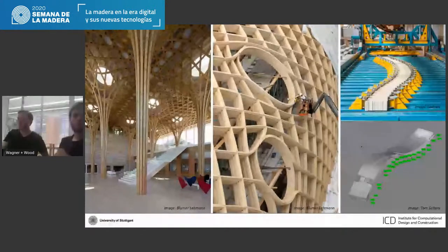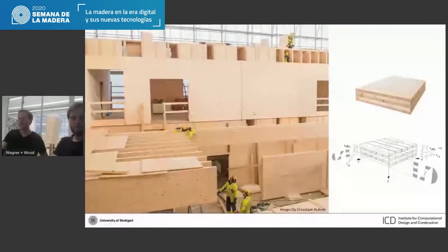But production still remains a bottleneck. To produce curved elements is complicated, and it also requires a lot more material and expertise. And as a result, larger sheet surfaces like CLT become very standardized and rectilinear, which works in some cases, but it fails to take advantage of the curvature that we can gain structurally and aesthetically.